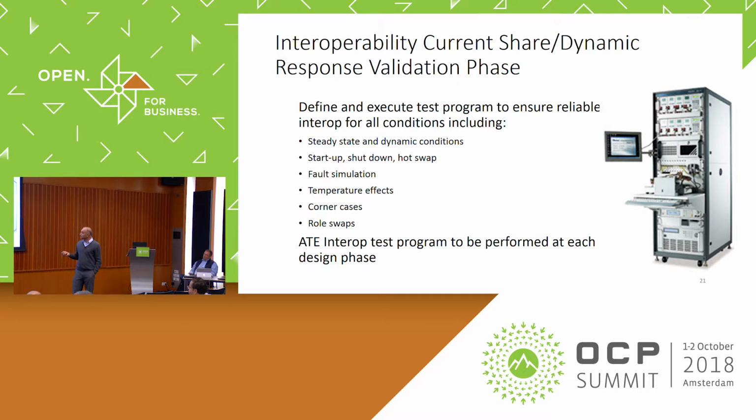So we look at this. The things we should look at is that we talked about the steady state operation, dynamic operation, startup, shutdown, hot swap, fault simulation, temperature effects. I mean, this plays a whole part in the power supply design, the components behave very differently at different temperature extremes. We need to look at the corner cases, role swaps. So just to say that the ATE will go a long way to address that.